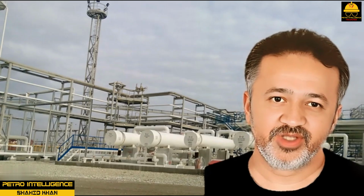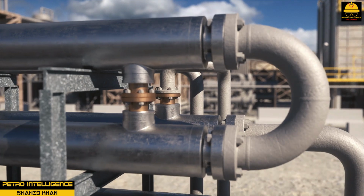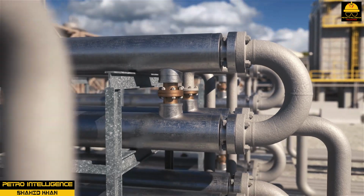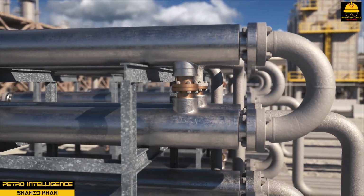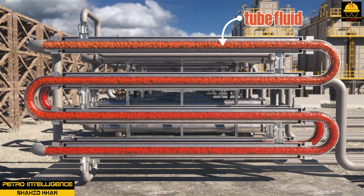Double pipe heat exchanger. A simple design for heat transfer is found in a double pipe heat exchanger. A double pipe exchanger has a pipe inside a pipe, as shown in the picture. The outside pipe provides the shell, and the inner pipe provides the tube. The warm and cool fluids can run in the same direction, parallel flow, or in opposite directions, counterflow or countercurrent. Flow direction is usually countercurrent because it is more efficient.